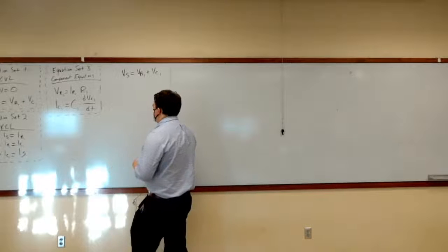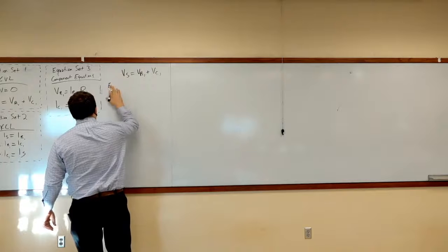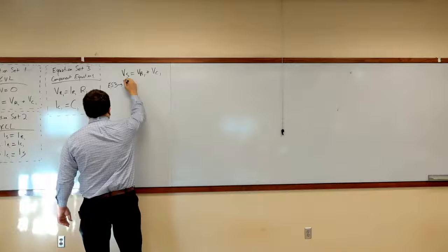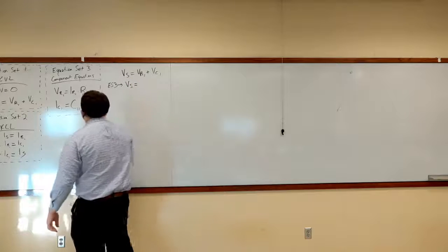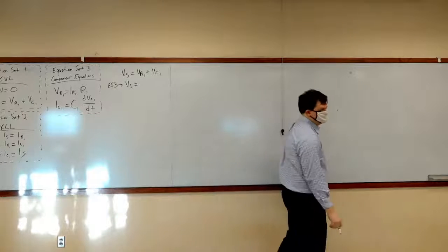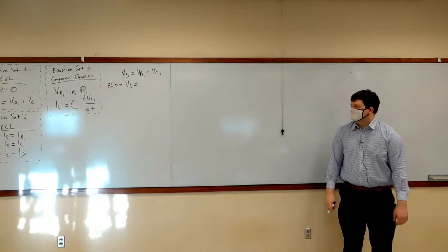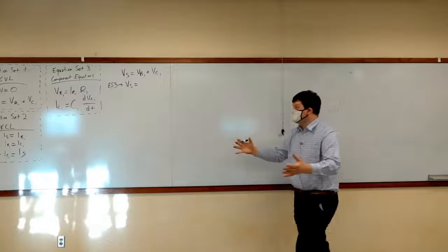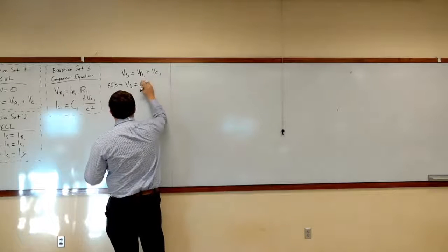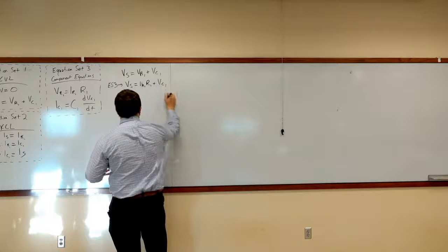Now I'm going to bring in equation set number 3. So I'll write equation set 3. Using equation set 3, what can I do with VR1? I can substitute it. What does it become? Yep, IR1 times R1 plus VC1.